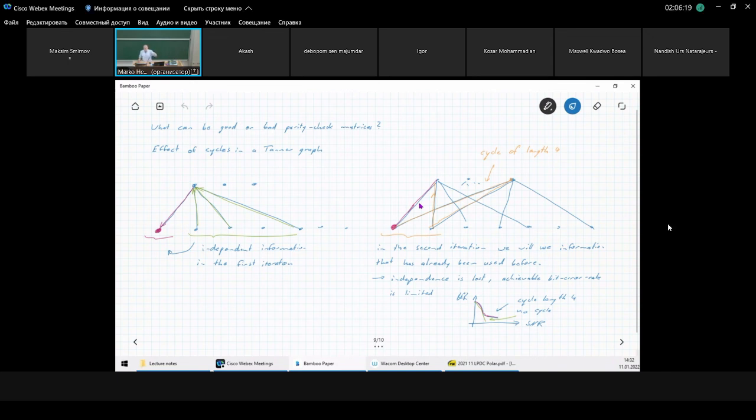So that's one other point that we have to consider when choosing certain parity check matrices. So we basically have 2 constraints. We don't want the short cycles, but on the other hand, we want large minimum Hamming distances. So those are the 2 optimization constraints which will at the end result in certain structured matrices.